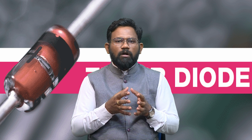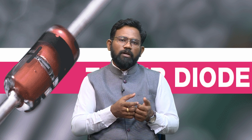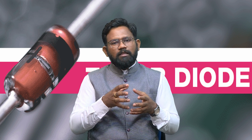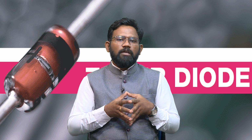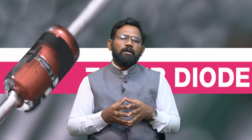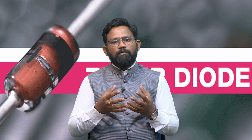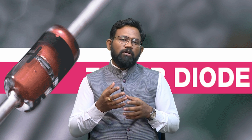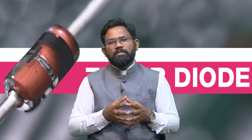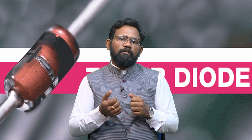So, by applying the concept of the maximum current and the minimum current and the maximum source voltage and the minimum source voltage, we can derive the formula from the circuit, and in this case we have derived the formula, that is R is equal to EI minus E naught upon IZ minimum plus IL maximum. So, the value obtained here is 30 ohm for the series resistance. From this we can find out the different values of resistance and the current or the voltages for different conditions by applying the concept of Zener for the varying voltages or the varying load.